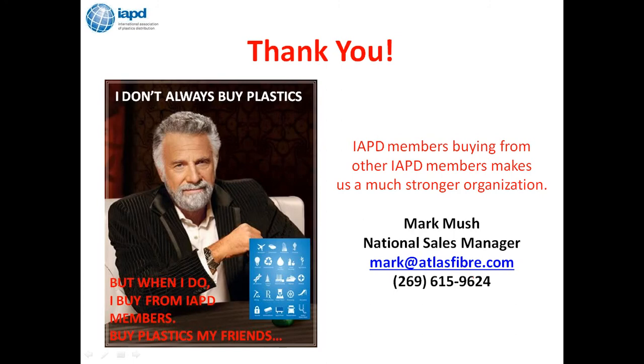It used to be for many, many years that FR4 was far and away 99% of the market. If somebody said G10, we just kind of took it for granted that they really meant FR4. I would say over the last decade that has changed fairly dramatically, and that the use of the pure, true, or non-brominated G10, any way you want to call it, but just regular old G10, non-brominated, is probably now 15 to 20% of the marketplace. And the brominated, or the flame retardant, the FR4, is the balance of it. Still more popular, but you'll see the true G10 growing more and more all the time.